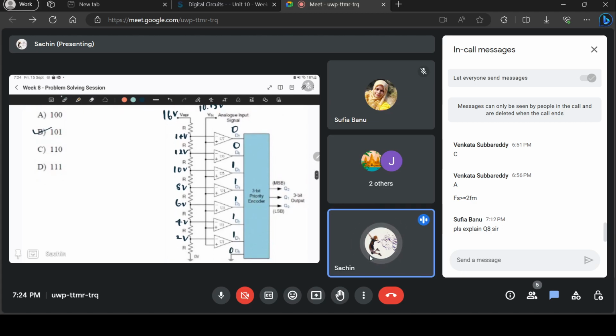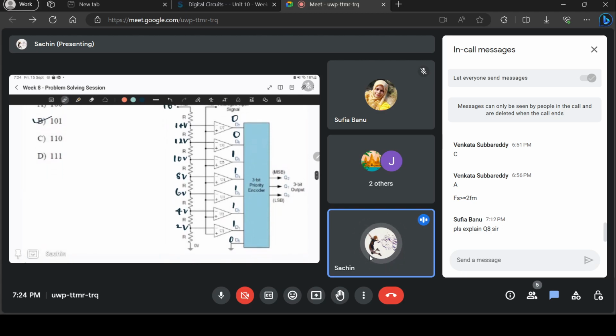Now, there was a circuit called the priority encoder that was taught in previous classes, right? What this priority encoder will do is check which of the input lines are high. Among these, there are lots of input lines. D1, D2, D3, D4, D5 are all high, but it will give priority to the largest number.